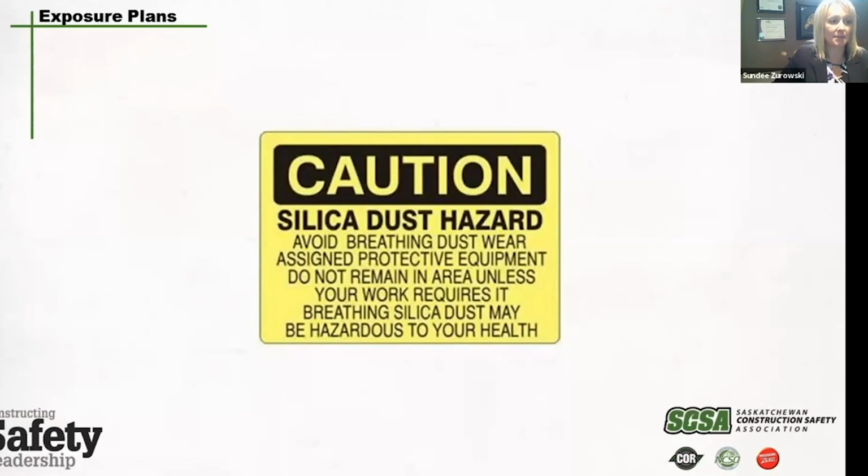So you want to identify what silica is, purpose of the exposure control plan, responsibilities, risk identification, assessment, and control, a description of the tasks in the workplace that involve exposure to respirable crystalline silica, education and training, safe work practices, a description of engineering controls, work practices, and respiratory protection used to limit employee exposure to respirable silica for each task.